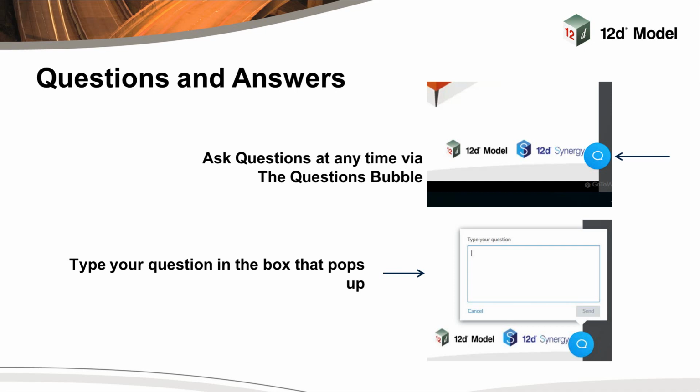So Mohammed has asked, when you pick up the detailing and plot into your frame, are we able to view every detail on the drawing? Yes, it's pretty much what you see is what you get. If you've referenced a frame to a view, whatever is activated and turned on in that view, apart from rasters, will automatically appear in the preview. And similarly, if you've entered either user-defined text in the title block or it's referencing a drawing register, it's a what you see is what you get type of situation.